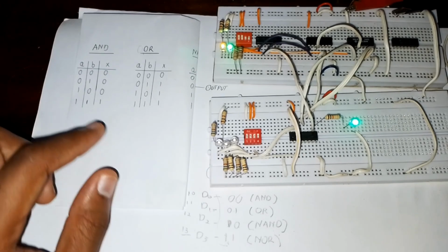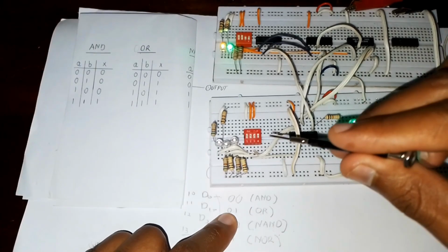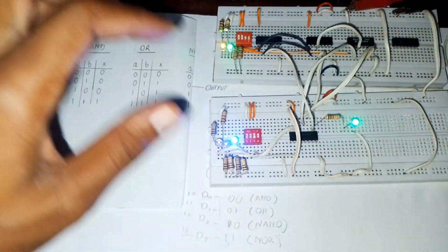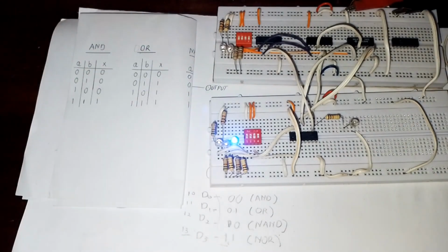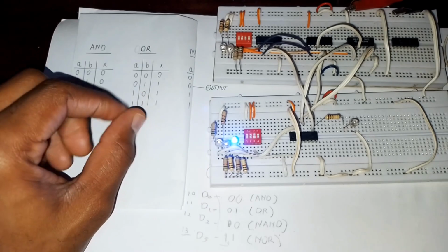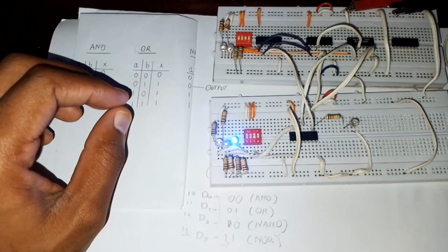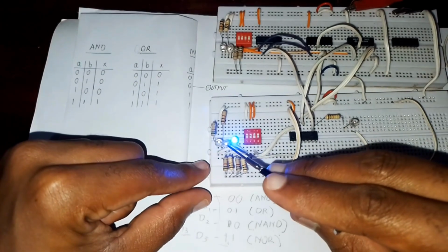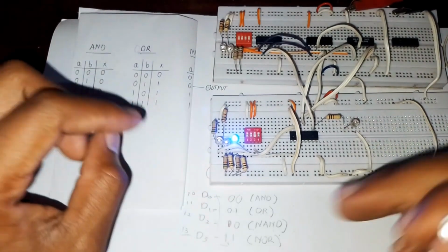Let's go to our second one. It's an OR gate. So the code that we have to place on our select line is 0, 1. So let's place 0, 1, and let's turn this off like that. The OR operation operates in the sense that if either of the inputs is 1, it's going to give you a 1 output, and if both of the inputs are 0, it's going to give you a 0 output. This is the code for OR, so we are doing the OR operation, not the AND operation or any other operation.